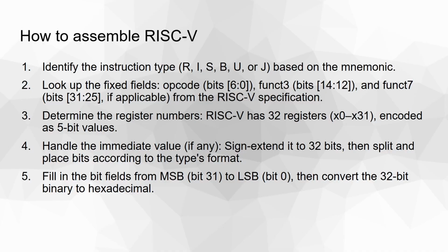And I can't describe it perfectly well here, but if you look at the RISC-V specification, you'll notice that a bunch of different instructions that use immediates have your immediate value bits just spread all over the instruction encoding. And that's for a good reason. It makes it easier for them to create 16-bit instructions, but it does make the instructions look a little bit weird because you have your immediate values spread across 3 different areas and then you have to concatenate it together. Can be a little annoying.